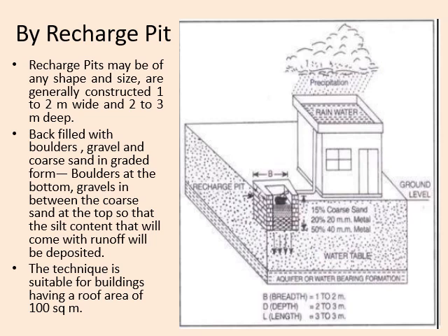So first, by recharge pit, we can harvest some rainwater. Recharge pits are of any shape and any size. There is no fixed dimension. They are generally constructed 1 to 2 meter wide. Width is 1 to 2 meter, meaning breadth, and 2 to 3 meter deep. Length can be 3 meter on an average.